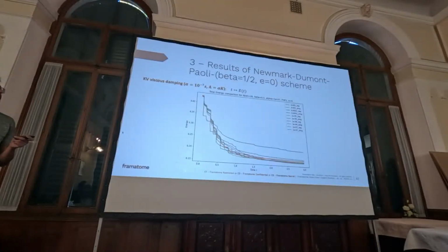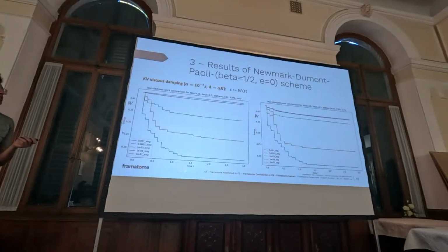And if we try the Kelvin-Voigt viscous damping, it's a different result since we involve the higher space derivatives for viscosity, and we have pretty much similar results, except for around 10 to the power of -7, where we see the clear convergence to the theoretical result in the singular mass matrix, but also an almost constant function for the regular one.